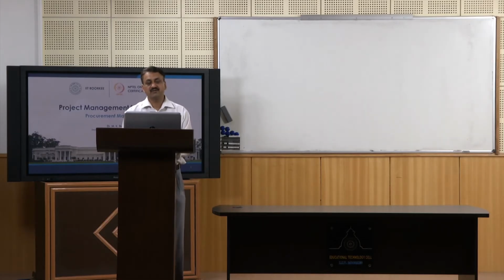There are different types of methods available. For example, if you want to measure the central tendency of the process, then there is something called the X bar chart. You can use the X bar chart. For measuring variability, you can use the R chart. If not the R chart, then in some situations you can use the S chart, called the standard deviation chart.